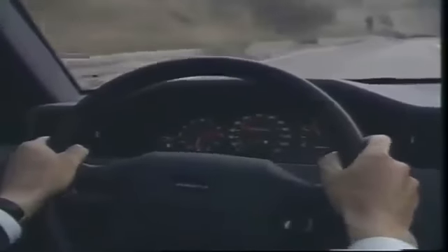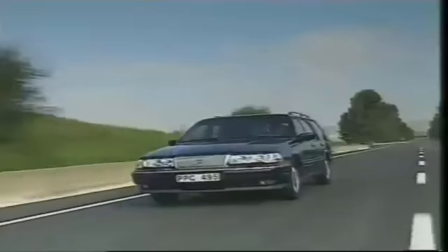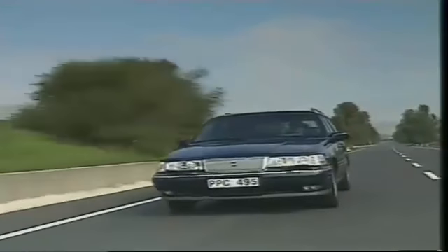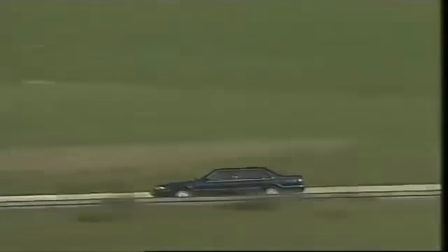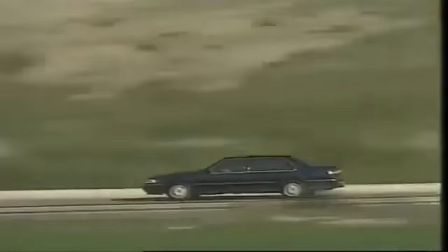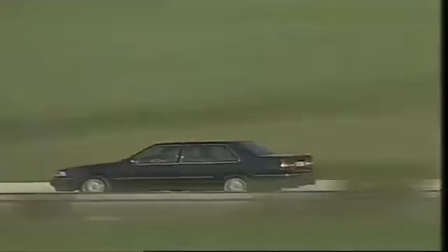Most cars have positive caster because it makes it easier to travel in a straight line with minimal driver action. But as positive caster increases, more and more effort is needed to turn the steering wheel. A small amount of negative caster reduces the steering effort needed at low speeds, but can make a vehicle wander at high speeds. In all cases, the manufacturer's specifications should be followed.